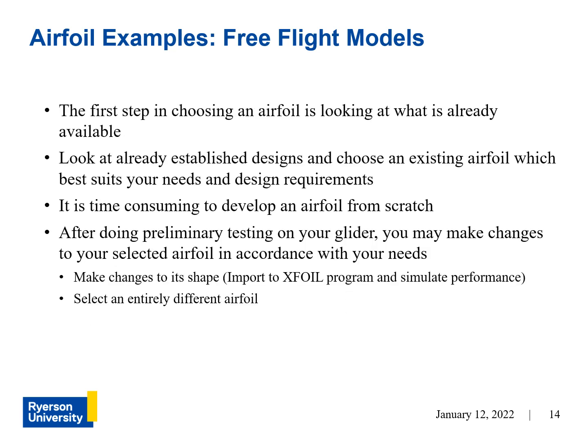So the first step in choosing an airfoil is looking at what is already available. You look at already established designs and you just choose whichever one best suits your needs and the design requirements. And you do this because it's time consuming to develop your own airfoil from scratch.